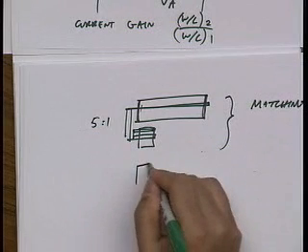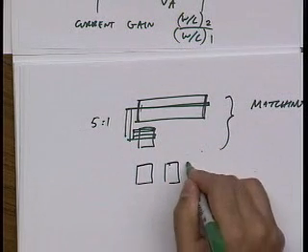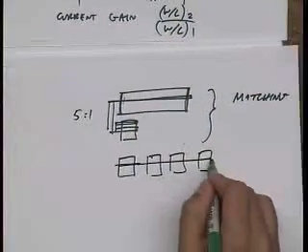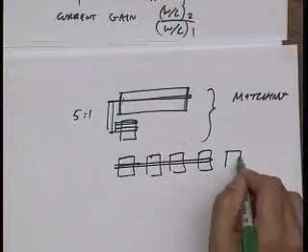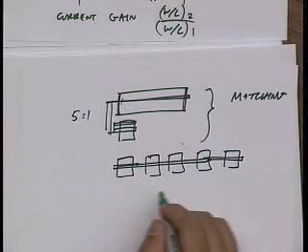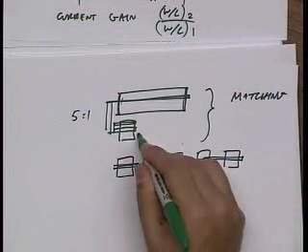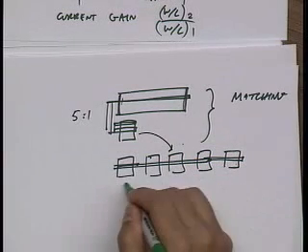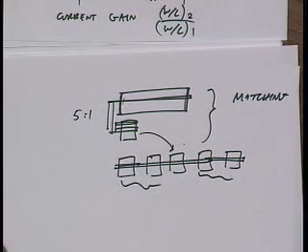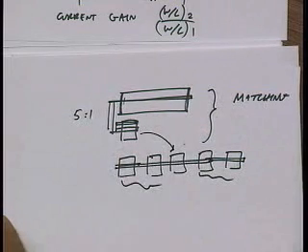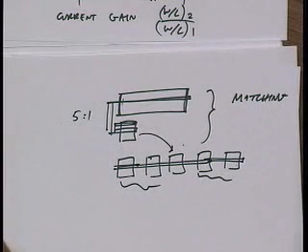And the way to solve that, of course, is very similar to what we talked about in the first couple lectures, is we realize this device with actual discrete devices. And we can interdigitate the device, so this might be this device here, and these would be the output devices. Okay? And then you could put them on a quad to try to minimize gradients and play all the same tricks we did with our resistors.